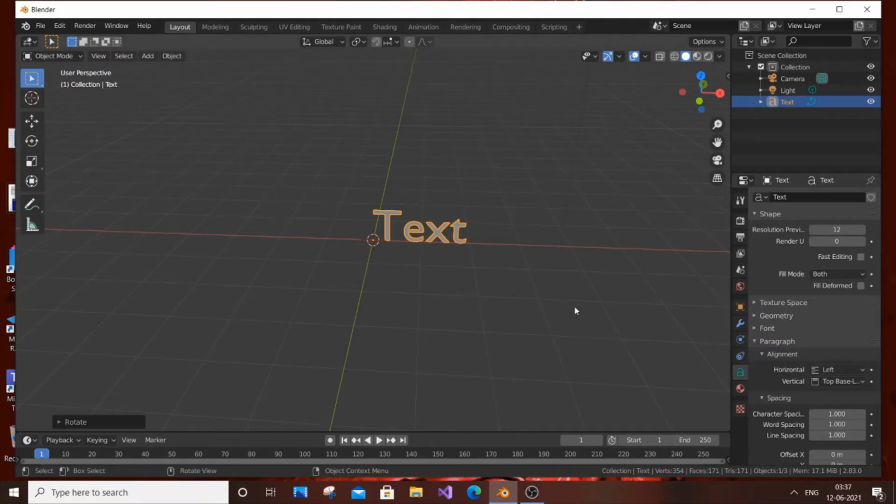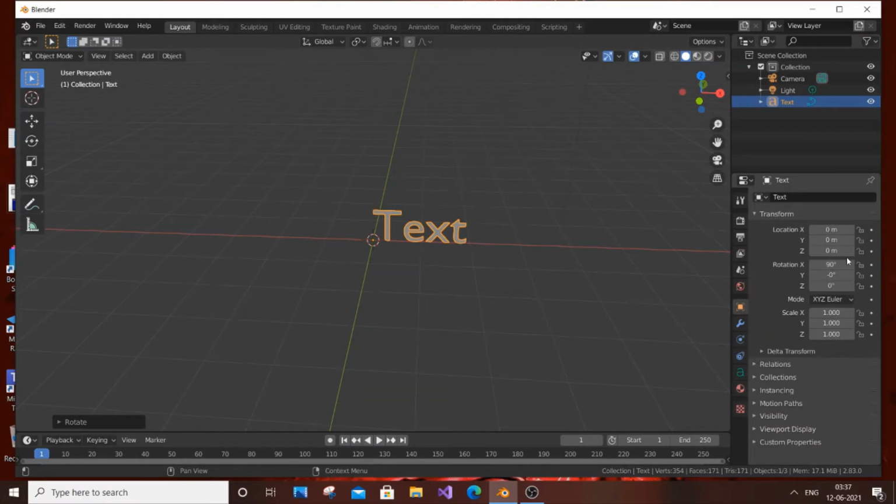You can also change it manually, okay? Go to this option, object properties, and here you will have rotation along X. It was actually 0 at first, which was the beginning, when it was laid on the floor. So if you don't want to press R, X and 90, you can just go here and change this value to 90. That's it. It's back to normal.